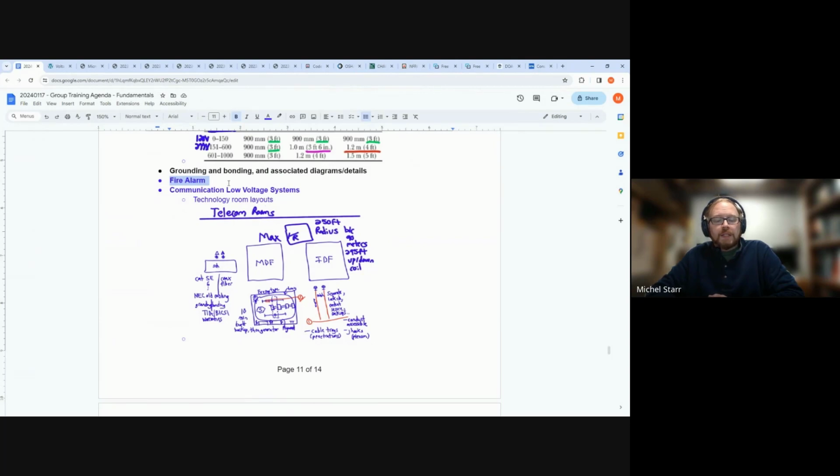Fire alarm systems can also have voice evac type functionality, and in some cases it is required. And again, that's pushing to the building code conversation. The aspect of a fire alarm in general is what you're trying to do is get people out of a building. So there are some buildings where people can't do that. They can't self-preserve, and so the occupancy classification and how the fire alarm system's reporting makes a difference.